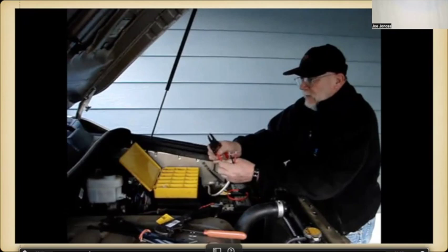Yeah, that's actually marine cable. The wire that's inside is tinned copper. When you use tinned copper with a tinned terminal, you need not solder it. It will not corrode. Because when you make a proper crimp, it anneals the wires together.